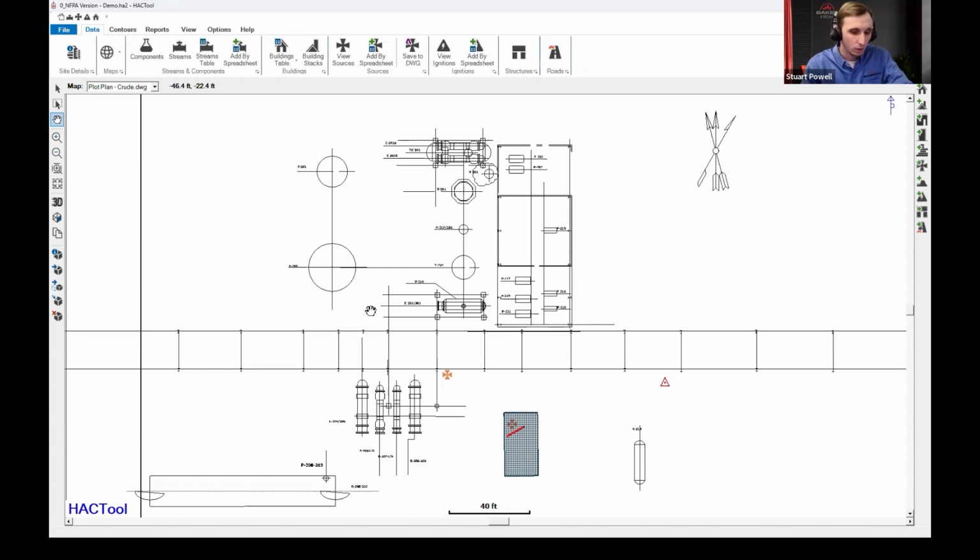That allows you to, if you add any release sources, and it's those sources that are going to generate our classified area boundary and our requirements there, any release source that you add to one map, if it's properly overlaid on top of each other, gets added to all the other maps in the stack. And so you can generate contours for a unit and also for the entire facility